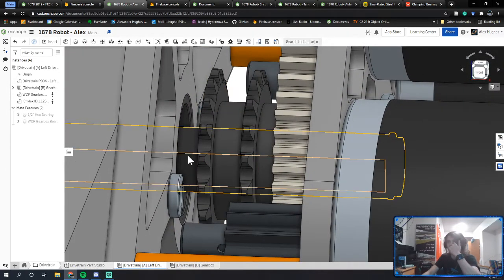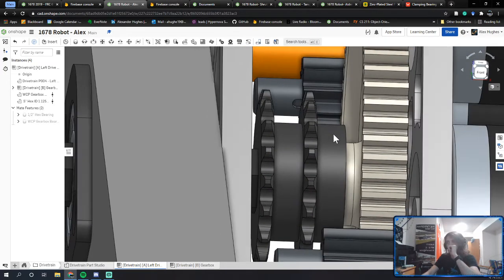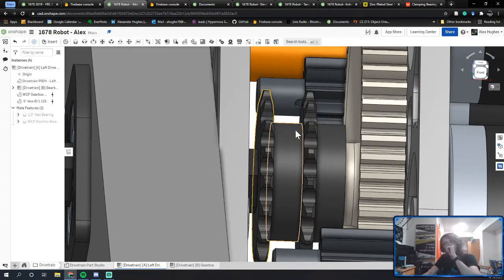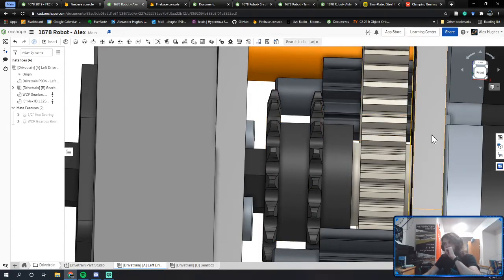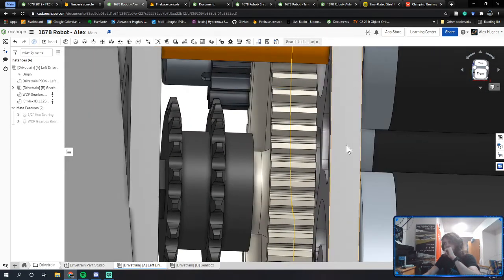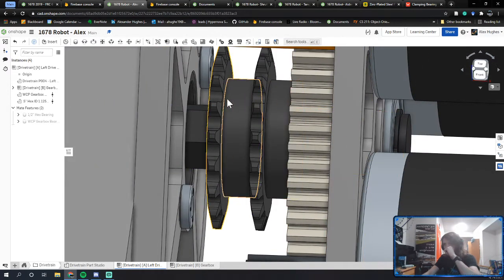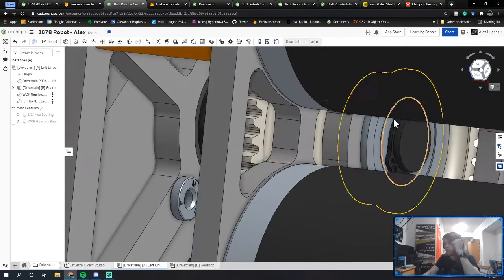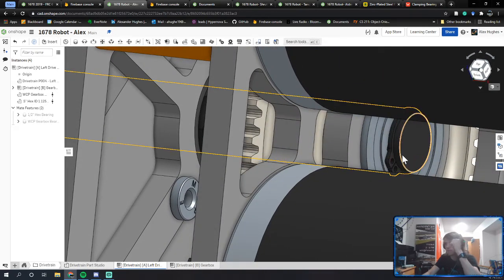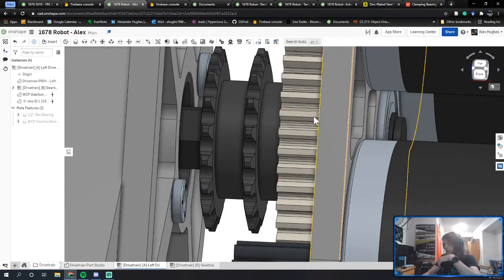Now, the reason we want to put a spacer in here is you've got to think, these sprockets cannot move to the right because they are anchored by not only the plate itself, but the shaft collar. Basically, any lateral force to the right is going to be prevented by whatever shaft retention you use here, in this case an E-clip. So you cannot push anything to the right.